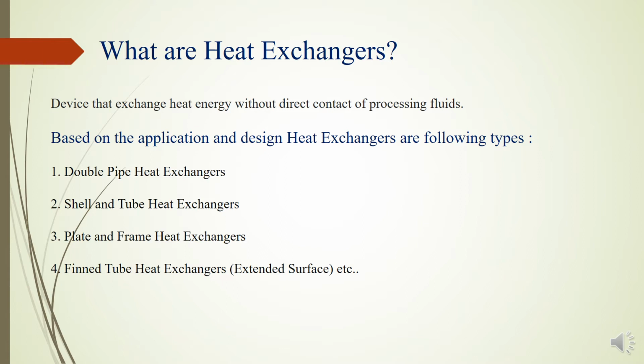Third one is plate and frame heat exchangers. Plate and frame heat exchangers contain a number of thin shaped heat transfer plates bundled together. The gasket arrangement of each pair of plates provides two separate channel systems. Each pair of plates forms a channel where the fluid can flow through. The pairs are attached by welding and bolting methods.